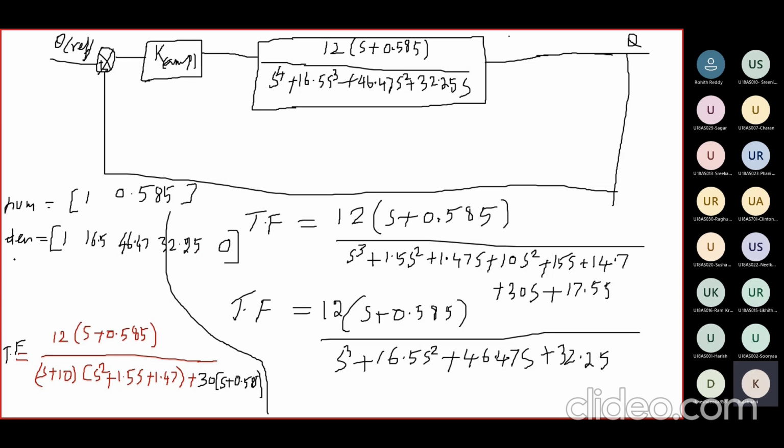Now my transfer function, if you consider these whole things g, then your g is equal to 12 times of my transfer function tf. I define numerator comma denominator. Now I sketch root locus of my g. I use this command, then we sketch the root locus for your outer loop control system.